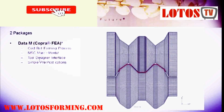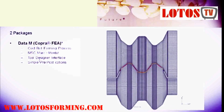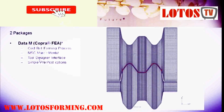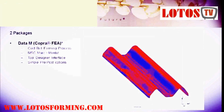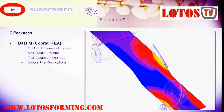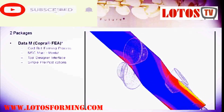And what it does is it provides the tool designer, the roll tool designer, with an interface with which to very quickly translate the tooling geometry and generate a mesh for the strip into the Marc solver. And as you can see on the right hand side, will show how a particular profile is being formed. Okay, there's also fairly simple pre and post processor options to analyze the data and to set up the material properties, if you like, and the mesh geometries.